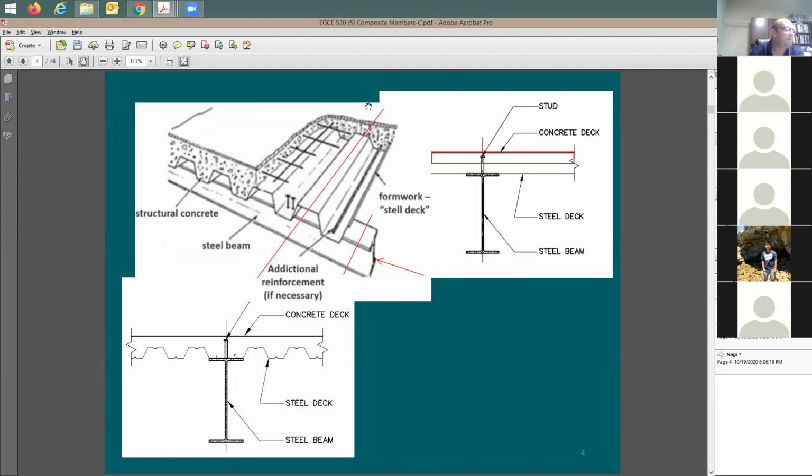I said, okay. How about for the girder? You can say, here's a girder section. So in this case, this is going to be here again, the girder section. You're going to see here the concrete is going to be 50% of the concrete through the deck is going to be coming down like this, which means all of this is going to be the concrete that you can consider in your analysis when it comes to the moment of inertia. Why do I know that this is going to be 50%?